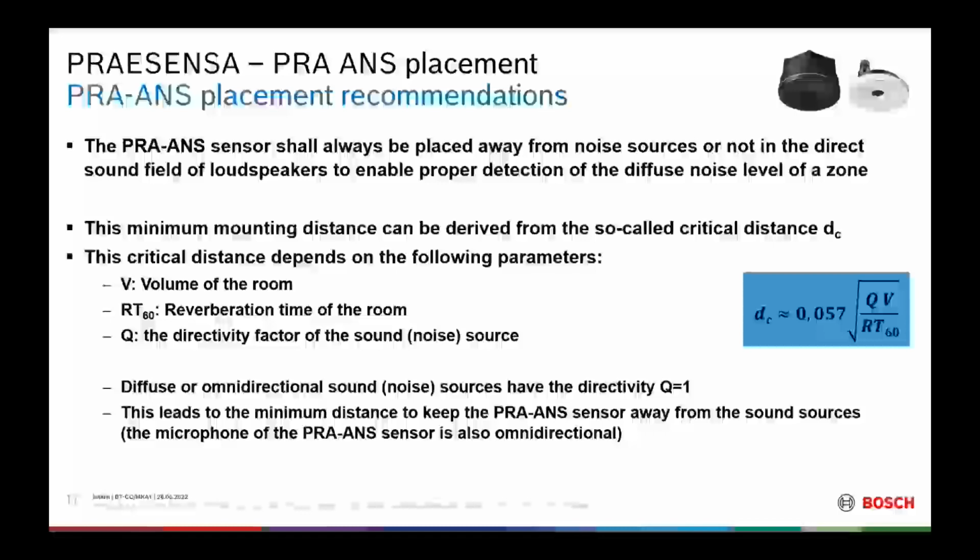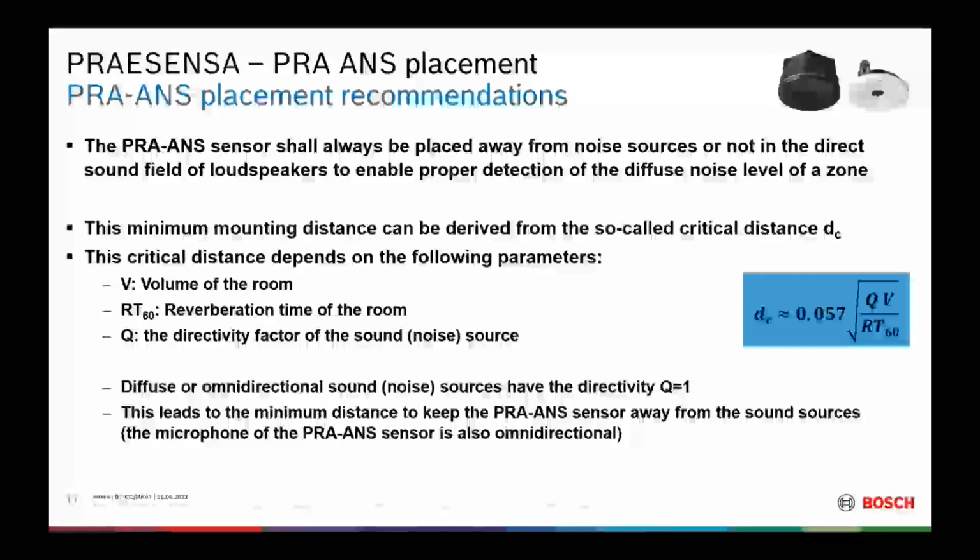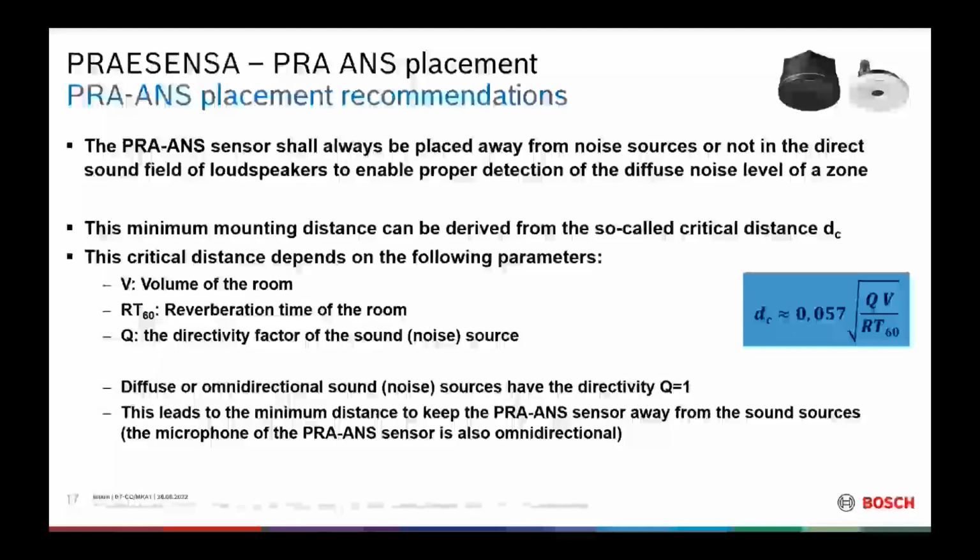So we take into account to derive this distance, because normally we now get the questions, of course: how far do I have to go away from my sound source? Where does my green area start, where I can place my noise sensor? This is the question we have to answer here. And the minimum distance, as said, should be beyond the so-called critical distance.